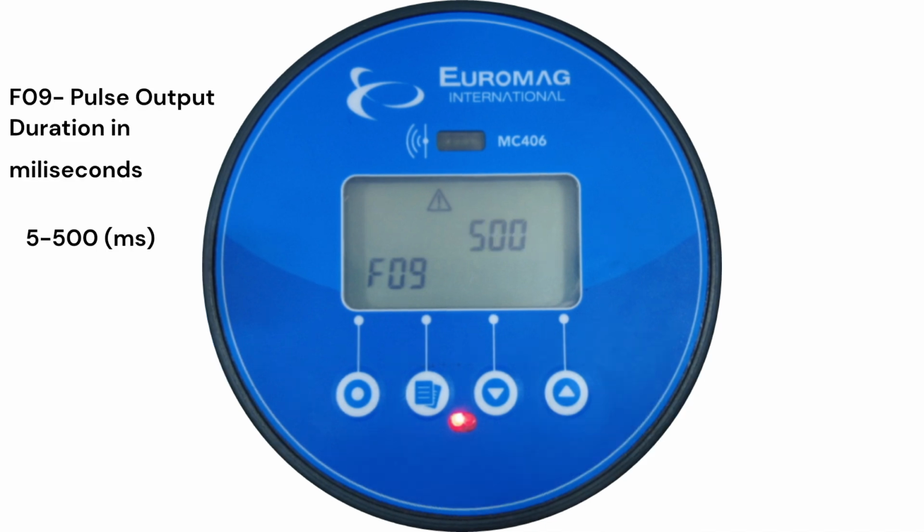Function number 9 is the pulse width, also known as the pulse duration period. Each telemetry manufacturer has different pulse width requirements. It's recommended to use the shortest pulse width that your telemetry equipment can sense because this setting can overload the battery and shorten the life expectancy of the battery.